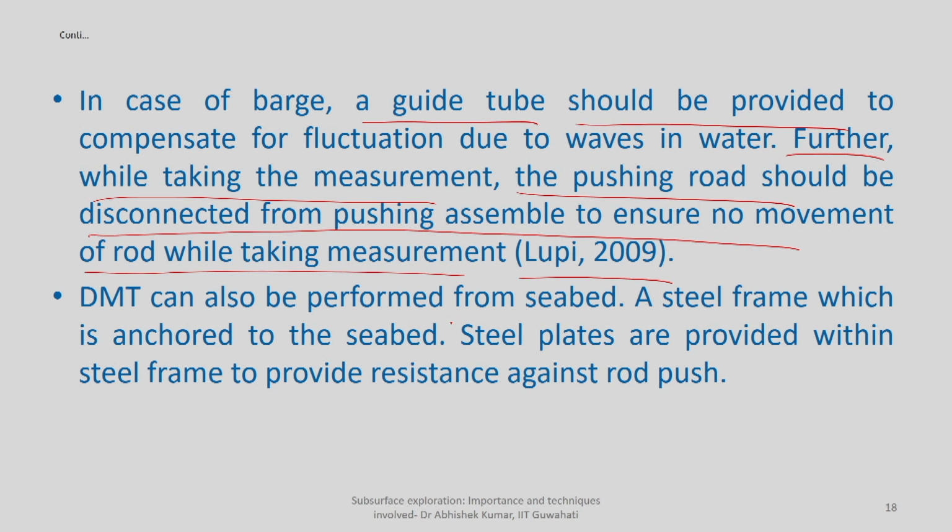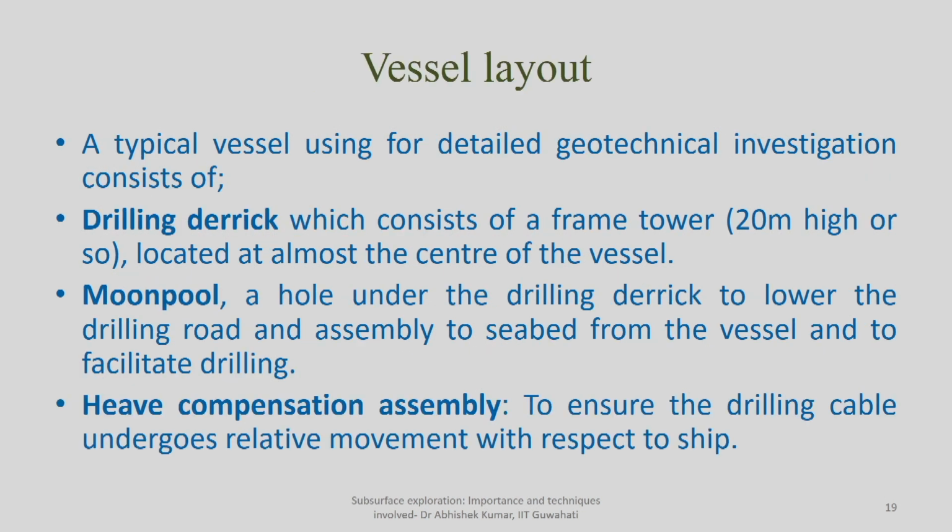As I mentioned, most of the geotechnical investigation you can do either from vessel control or from seabed control. You can do the test from the seabed. When you are doing it from the seabed, you have a steel frame which will ensure some kind of anchoring of the assembly with respect to the seabed, and then a steel plate which provides reaction towards pushing the rod into the medium.